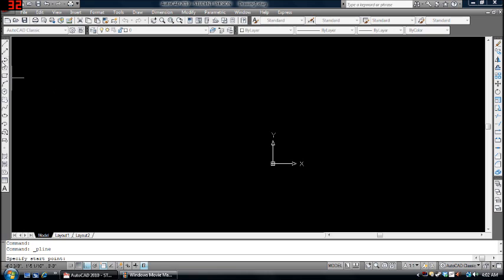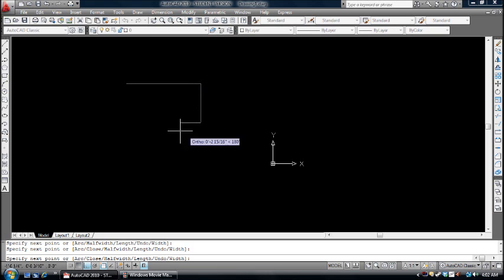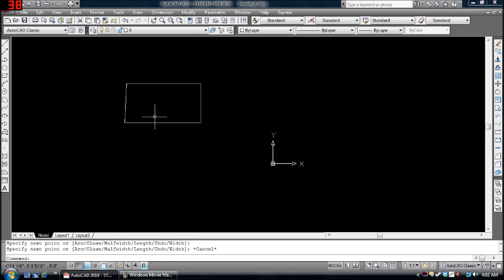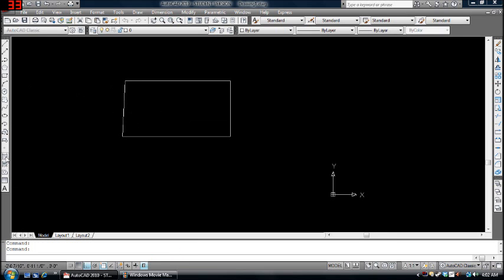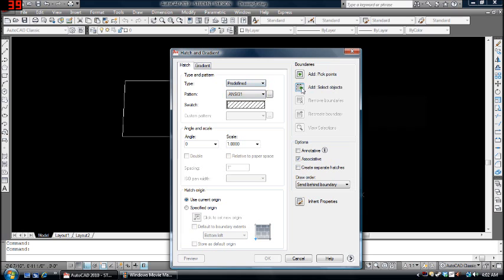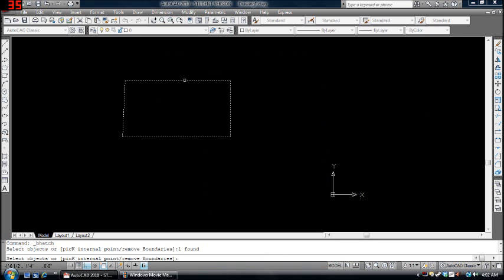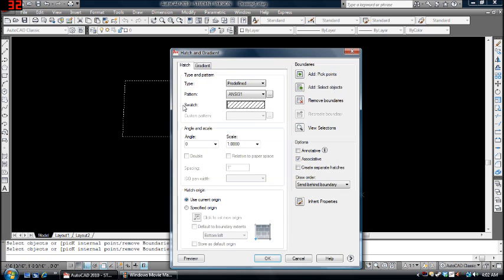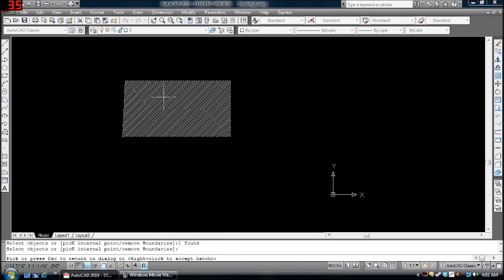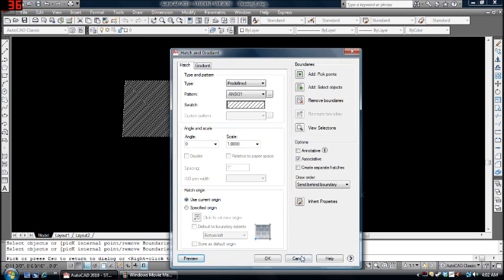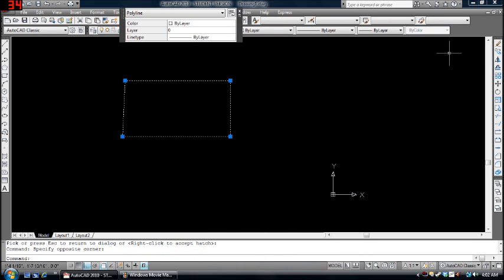This is polyline. Polylines are used to make closed boxes like that, so you can hatch it like this. Choose a hatch. Hit enter. Then you preview it. It'll look something like that. You can only do that if you have hatch patterns. I'll teach you how to do that at a later time, so don't worry about that right now.